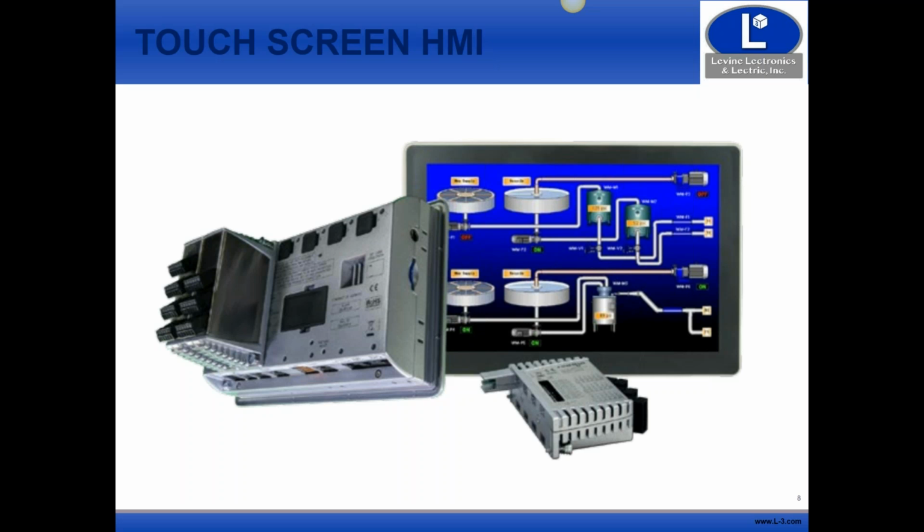and just finished a project in Auburn, actually, on one of the new buildings there, the engineering building, where we had to provide BACnet over to the Johnson Controls system. So at the time, we were using a different solution, and we ended up having to add a separate BACnet converter within the panel on top of everything else. So we got into every project we were looking at.